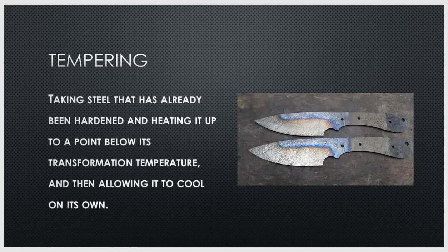So tempering is a method of heat treatment that we would apply to a piece of steel when we want kind of the best of both worlds. We want to keep that hardness, we want to keep that strength, but we also want to keep our ductility. We want to reduce brittleness. A perfect place to see where tempering is used is in blacksmithing, or more specifically, bladesmithing. Jumping to the Forged in Fire example that I gave in a previous video.